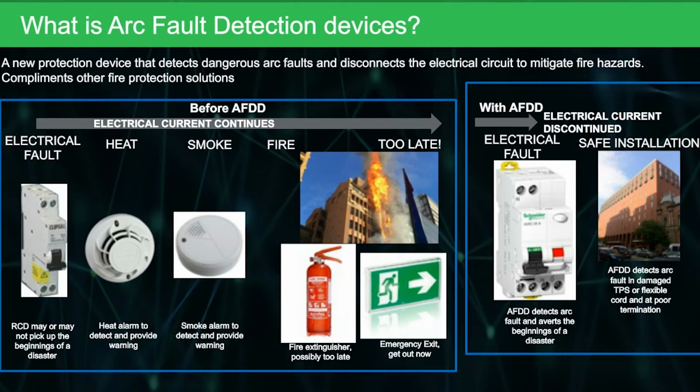The arc faults are small in nature, and Justin will explain that a bit later. They're usually a series or a parallel fault across broken or severed cable, and it's a very small arc that's created. But eventually, if it continues, it does actually carbonise the plastic insulation material of the cord or the cable. With the right conditions, eventually that will create a fire. The terrible part about that is that while it is arcing, it's smoking. When you're asleep, you don't smell anything, so you have a problem detecting that.